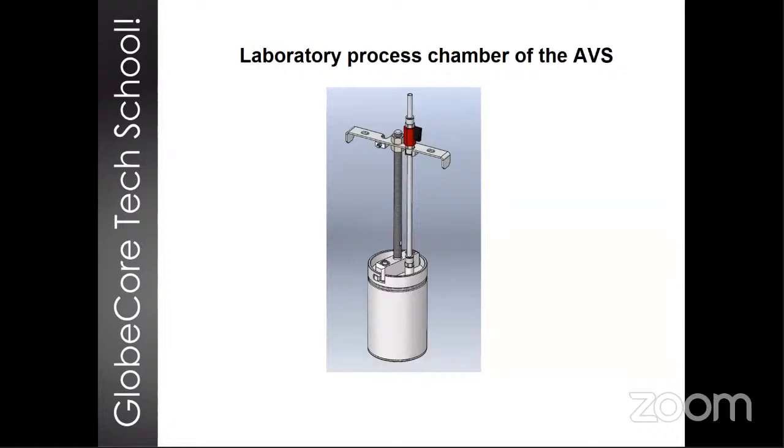Okay, so to work out the purification technology, all wastewater streams are different pretty much. Every stream contains a certain concentration and percentage of things. So we need to work on the technology before we start a full-scale treatment. We need to know how much of what reagent we need to add into the process, how many ferromagnetic particles need to be added into the process chamber. So we use something we call a laboratory process chamber.